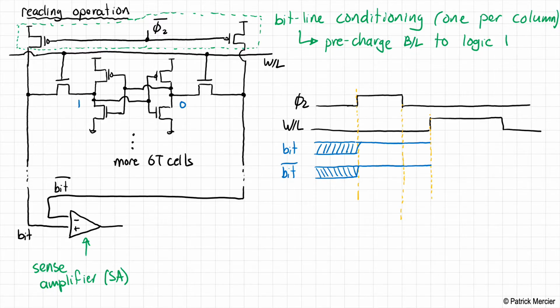It's static storage with dynamic readout. Okay, so far, hopefully everybody's on the same page. Now, what happens when the word line activates? When the word line activates, we engage those access NMOS transistors, and we have a little bit of a conundrum here,